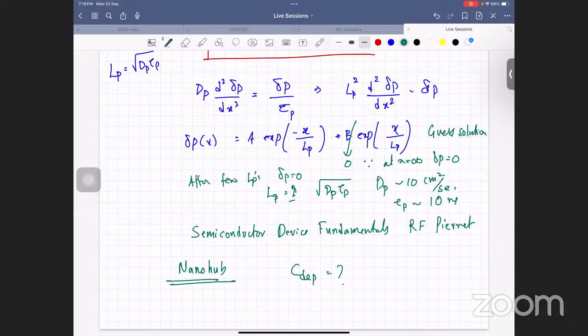Another way of looking at it is, if you increase doping concentration, what is the inversion charge threshold that you need to reach? For example, you have 10 power 15 doping, initially p-type. So for a PMOSFET, it will be ND, right? And then you consider ND equal to 10 power 18. But it's the acceptor doping concentration which is increasing, so you're talking of an NMOS device. The question says P-type MOS capacitor and increasing the acceptor doping.